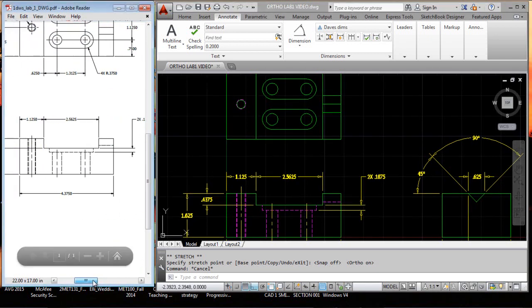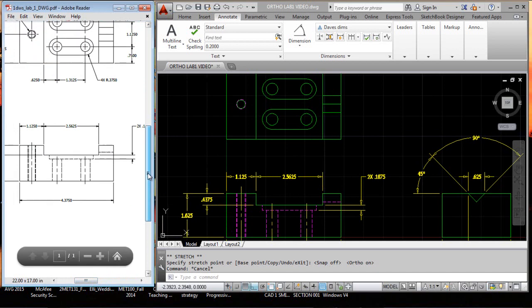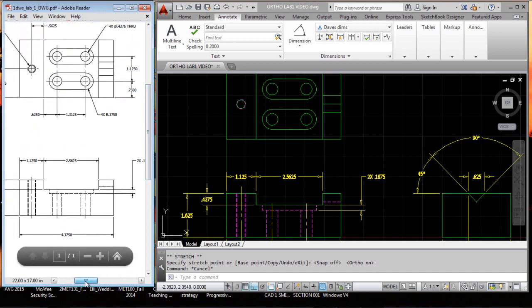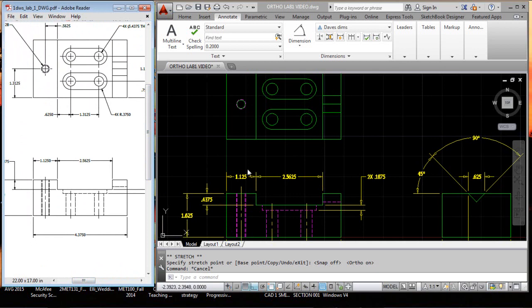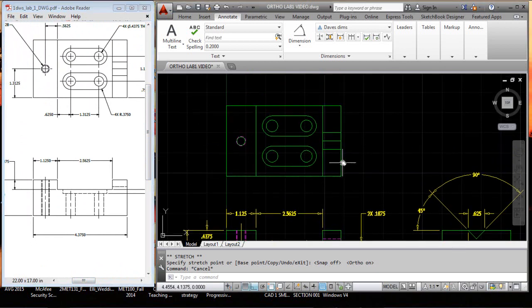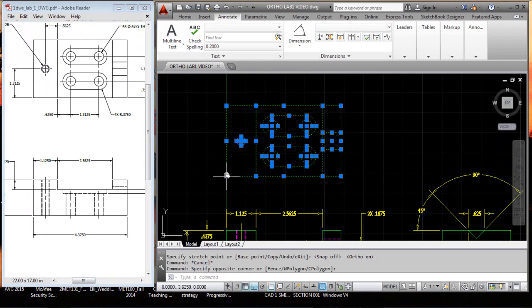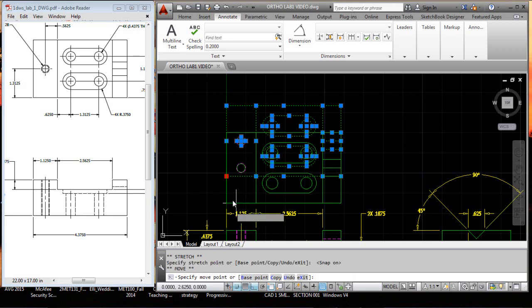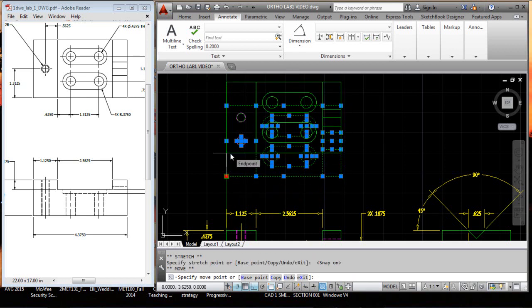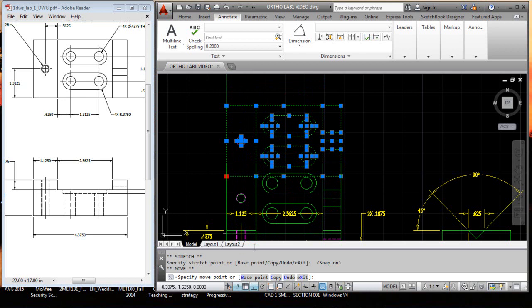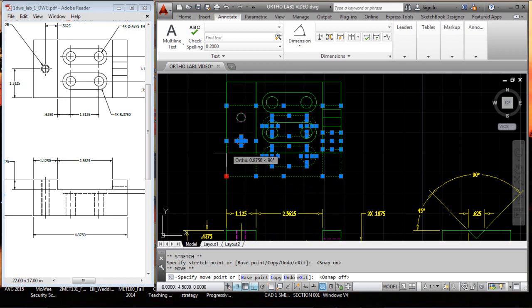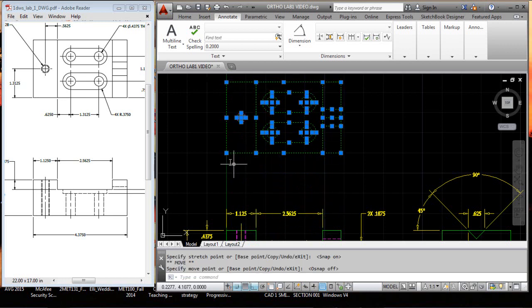Well, let's see. If we look at the rest of this drawing, it looks like we're only going to need one here, but we don't have enough room here. So let's plan on moving this stuff, this grip. We want to turn the snap on. Oh, better hit the space bar one time, right? Got our snap on. Let's turn the O snaps off. And I think if I put it right there, we should be fine. But that lines this bit up with the grid.